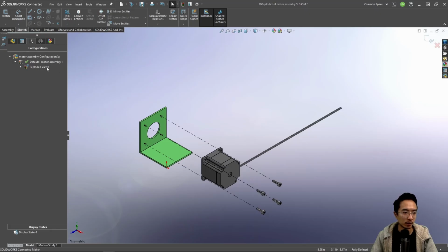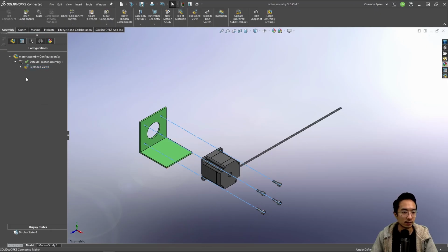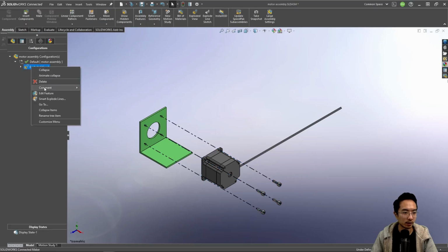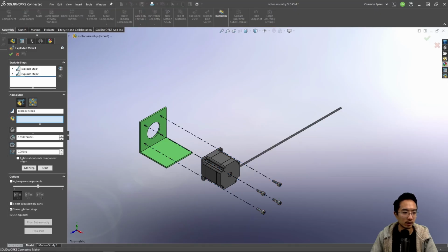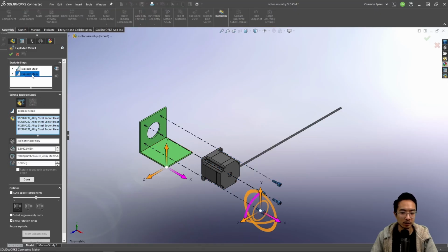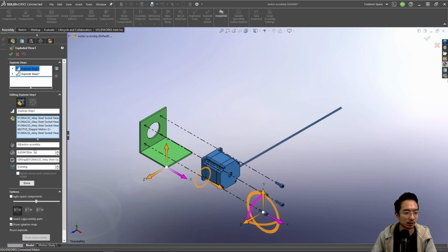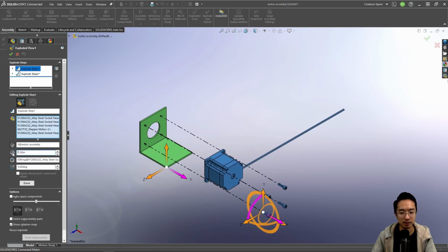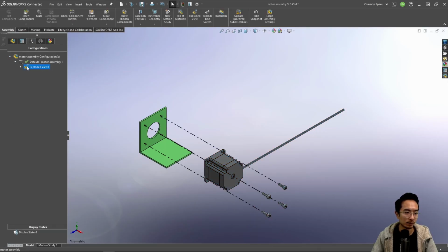Okay, so we could come back here. Let me just exit the sketch. But if you come back here and you try to edit your feature, notice you could come back to modify your steps. You could maybe specify an exact distance you want, maybe 7. And then here you could say like 7. So you could be very exact with your spacing.